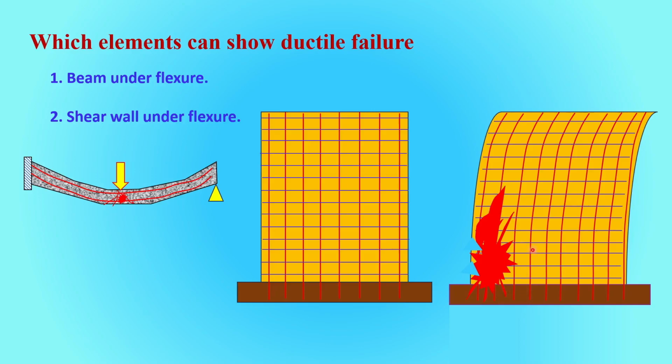Now shear wall is a deep beam we have discussed in the previous slide. So its depth is here to here, which is the length of the wall. As the beam is deep, it undergoes large flexural hinge formation and it can dissipate a large amount of energy while it is failing or when it is showing nonlinearity.